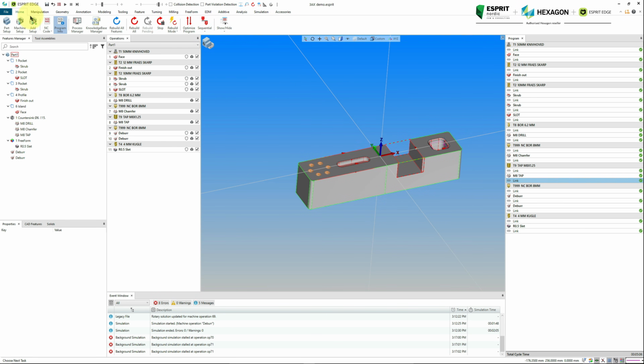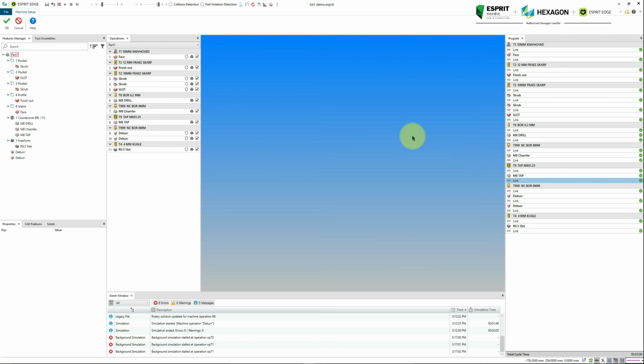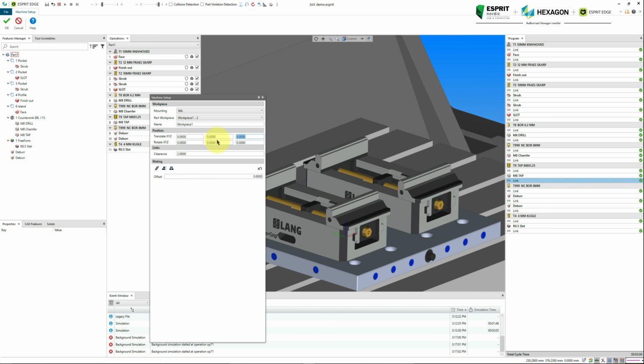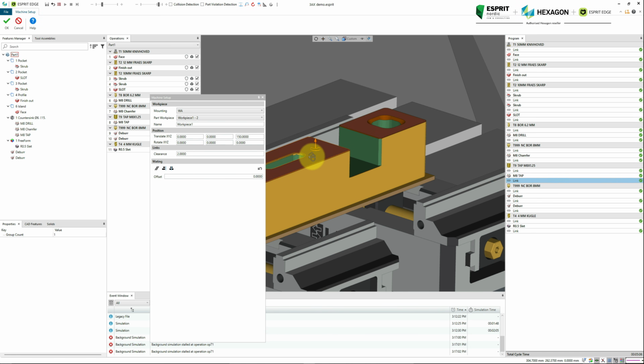Now on to the second side of the part. Here I'm using the Add Setup button located in the Home tab. This will create a clean setup and I only need to mount a workpiece. Here the stock will follow the part from the first setup, so if any changes are made on setup 1, the stock will automatically be updated on setup 2 and the toolpaths will also be updated on setup 2. Simply place the part as done earlier in the video.